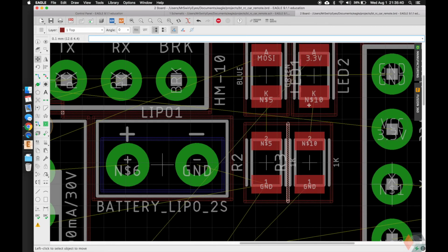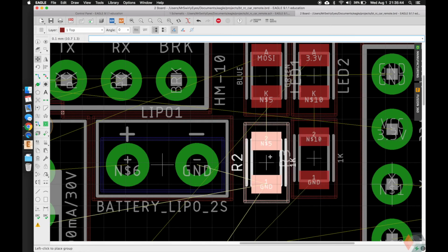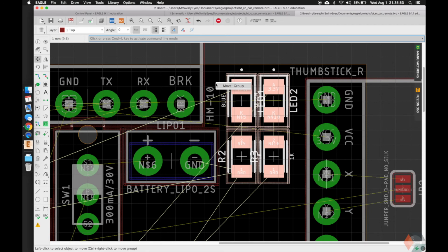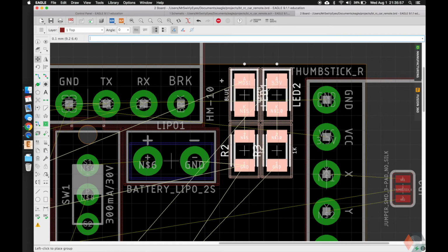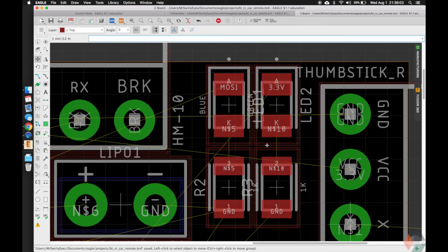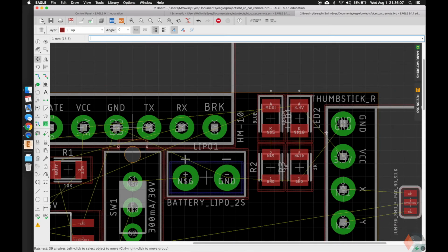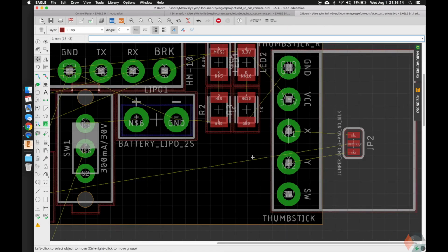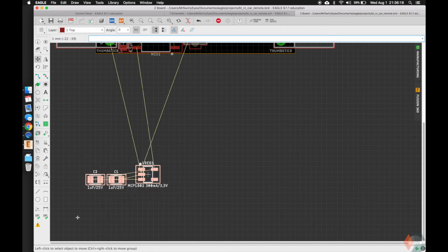Make sure they're not too close. I'm going to push these guys up pretty far. Here. Should be good. The DRC isn't yelling at me. Should be fine. I'm going to do a rat's nest now so that everything readjusts. That's good. So this is going to connect here, which will make sense with our power supply. We're going to put it right here. And this jumper is going to go somewhere over here probably. Let's go ahead and move all of these closer.